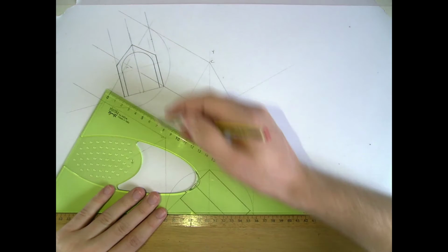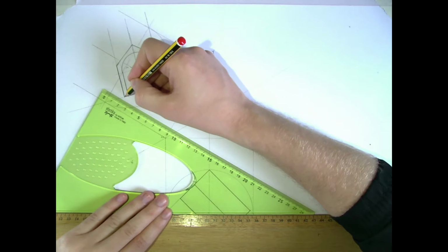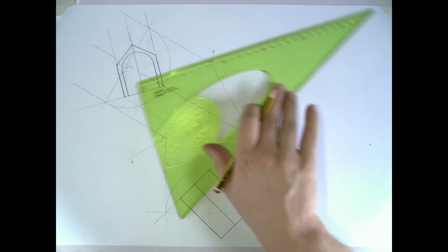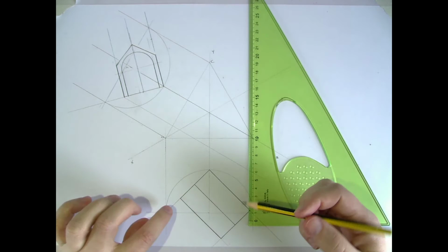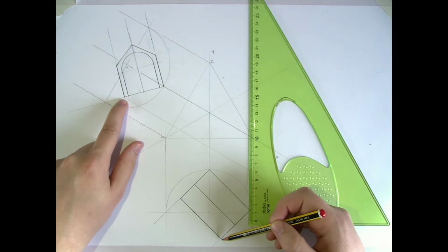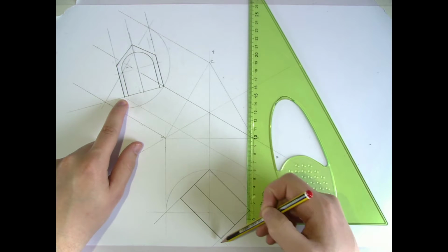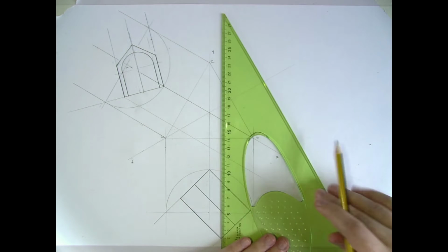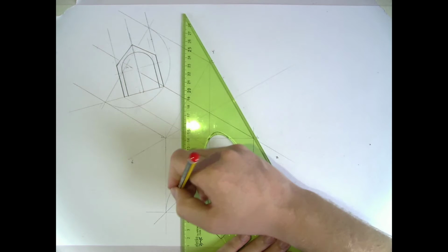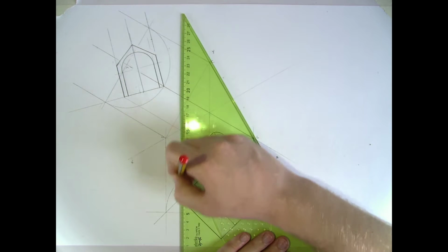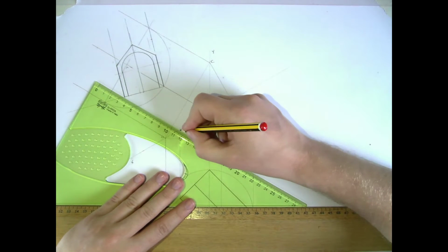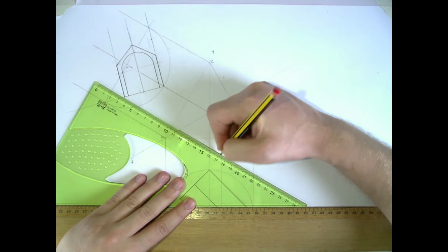So we're going to be taking this corner point here, projecting that line down into the axonometric views, and then locating the same points. So this point here is a point view of this line down here on the bottom, where it's sitting on the ground. So we can project those points up. That's 1 and 2. So that gives me that bottom corner down here, so I can just darken that one and make it clear as to what's happening. So that's this point.